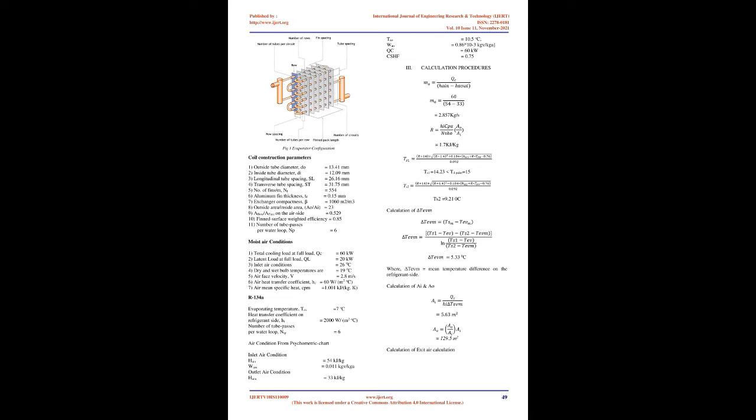2. Material selection and geometry. Aluminum and copper are preferred materials as they are good conductors of heat. Round seamless copper tubes are mechanically expanded into the fin collars of the secondary surface. The mechanical expansion provides a permanent metal-to-metal bond for efficient heat transfer. Tubes are staggered in the direction of airflow and only return bends are used, with no reduced tube wall in the bend radius by using hairpin bends.